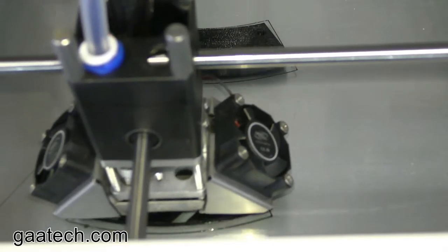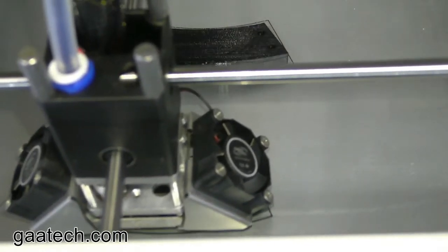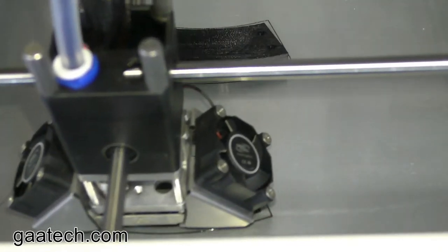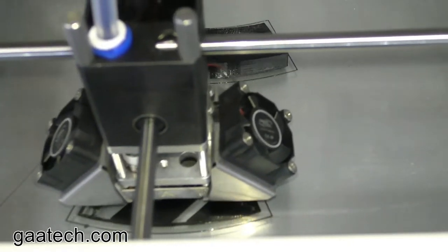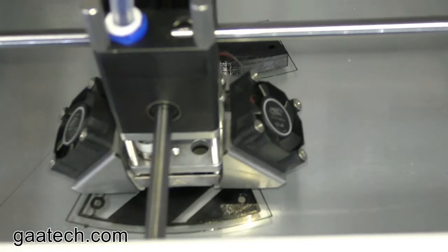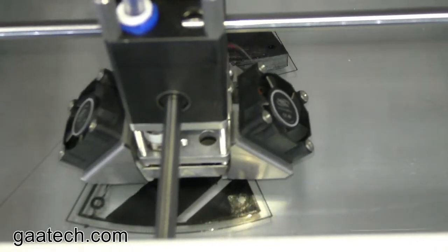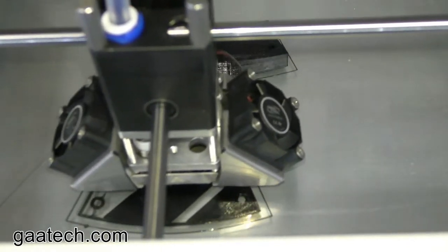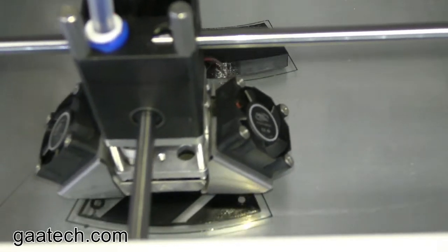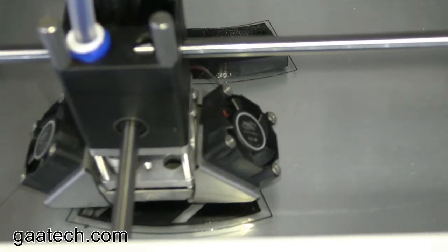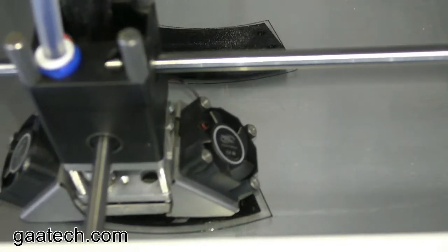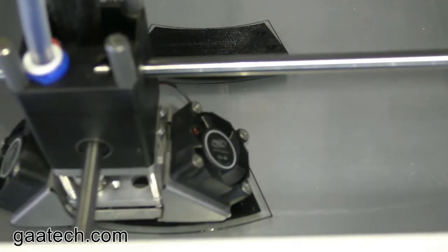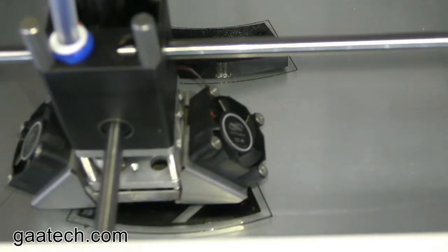Again, this is all customized in the printer software, and I'm using Cura, which is an open source platform, but they're all pretty much the same. And again, you turn the fans off to make sure that the hot molten filament sticks to the base better. And I can't quite remember on this print, the fans turn on after the second or third layer. I can't remember, but I'd have to check.